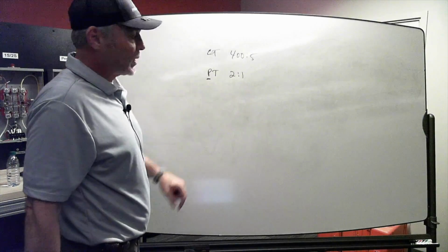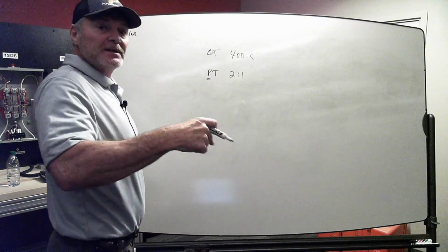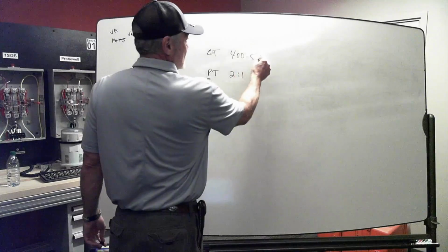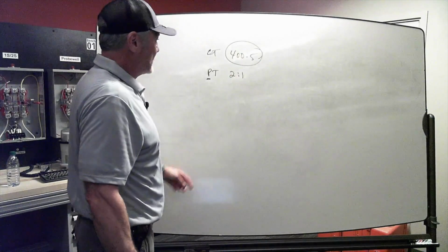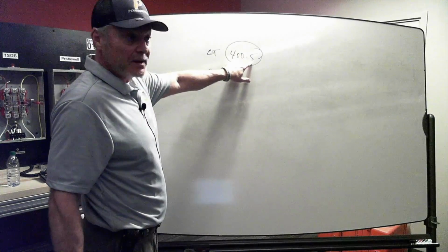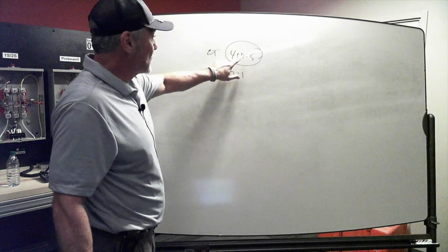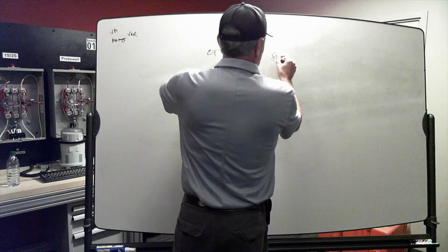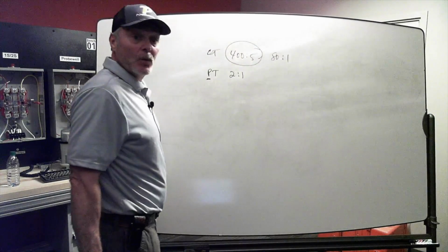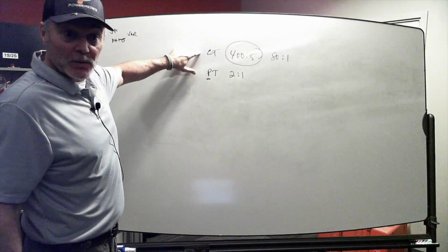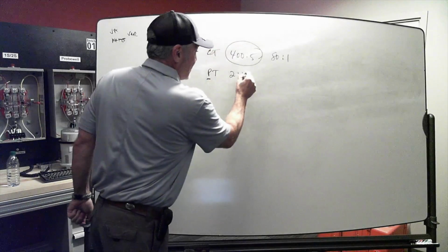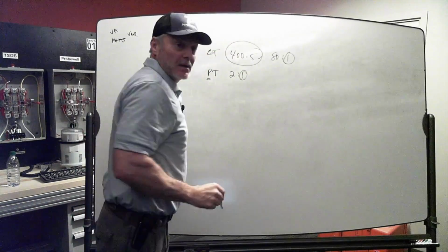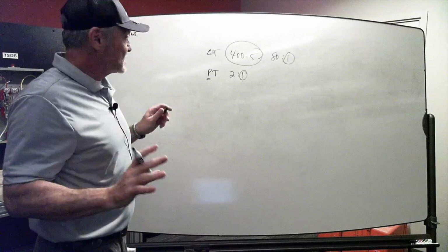So if I looked up at the pole and saw both of those, let's do a conversion on this one to make it simpler for us. If it's 400 to 5, I can divide 5 into 400 and I get 80, right? So really, I could say that's 80 to 1 on the current transformer. So now, having these ones on the end allows me to do this, okay?